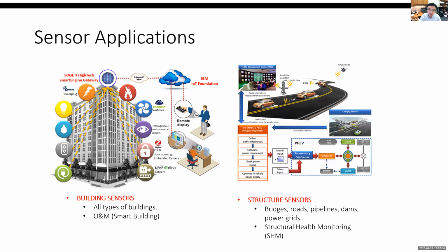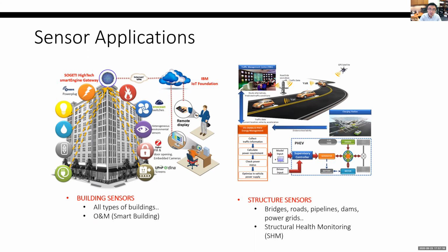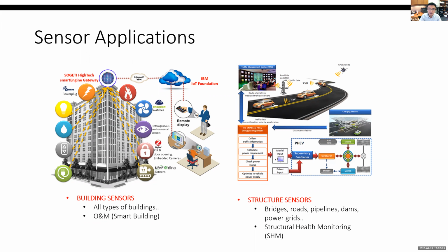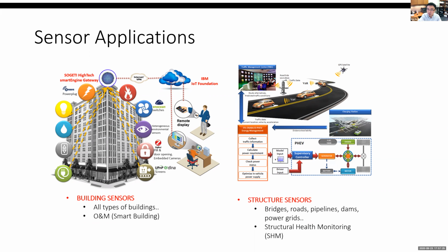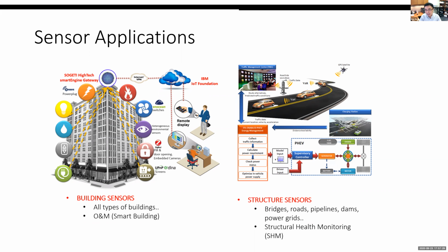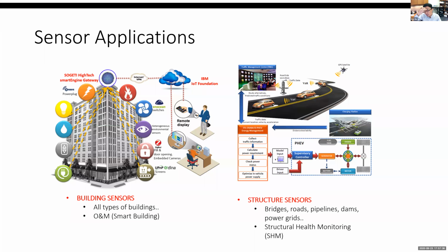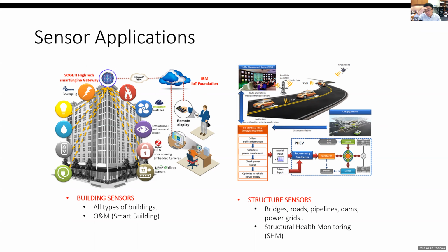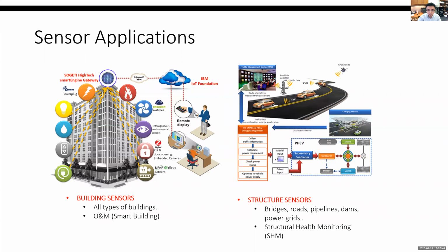That's embedded sensors. But most of the time we use multiple sensors such as vibrometers and accelerometers attached to the structure. We also talk about imagery-based sensors today, where we take high-resolution pictures or use a slow-motion camera to check the vibration and the rigidity of a structure. So those are all vivid, viable research topics today.